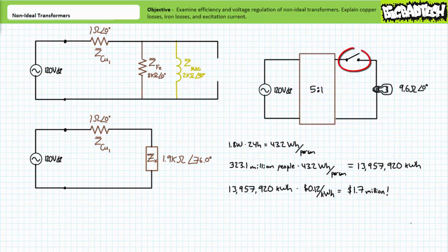The fundamental problem with our existing circuit is the location of the switch. As currently implemented, opening and closing the switch only cuts current in the secondary and not the primary, leaving the non-ideal transformer and all its modeled inefficiencies, including leakage paths in parallel, still active. A far better re-engineering of this circuit might be to relocate the switch to the primary side, effectively cutting the head off the snake by completely depowering the transformer in addition to the load in the secondary.